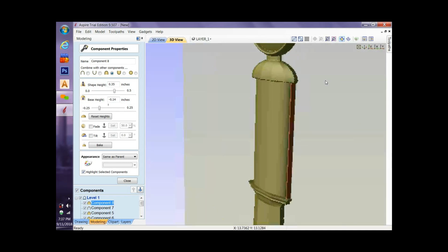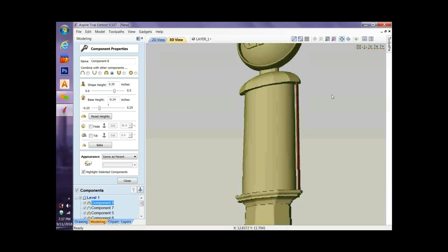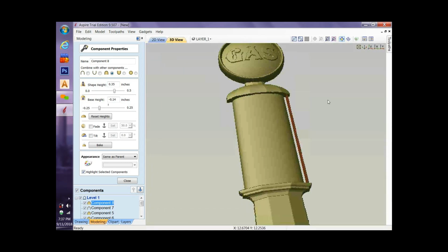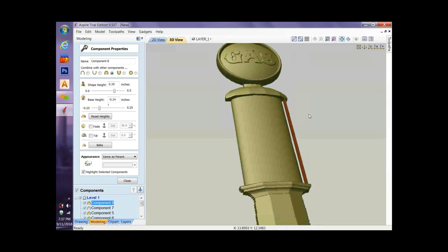And keep a nice straight 90 degree angle. If you use a taper, it's not going to be a flat 90, it's also going to have little marks in it. And those are horrible to try and get out unless you use another tool path, and I haven't had much luck with that. I usually get it to the point where it's good and I say, okay, I'm not going to mess with it anymore.